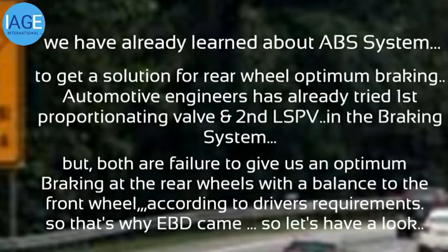Already learned about ABS system. To get a solution for rear wheel optimum braking, automotive engineers have already tried first the proportioning valve and second the LSPV in the braking system, but both failed to give us optimum braking at the rear wheels with a balance to the front wheels according to driver requirements. So that's why EBD came. So let's have a look.